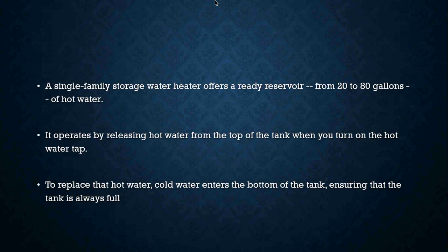Okay, single-family storage water heaters offer a ready reservoir of hot water. So think about it. They usually hold somewhere around 20 to about 80 gallons of hot water. Apartments may have slightly smaller sized water heaters. Condos, same thing. But homes, you're probably talking the upper end of about 80 gallons of water sitting inside your water heater. It operates by releasing hot water from the top of the tank when you turn on the hot water tap. To replace that hot water, cold water enters the bottom of the tank and ensures that the tank is always full.